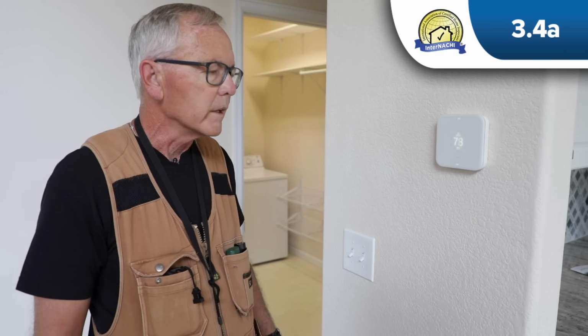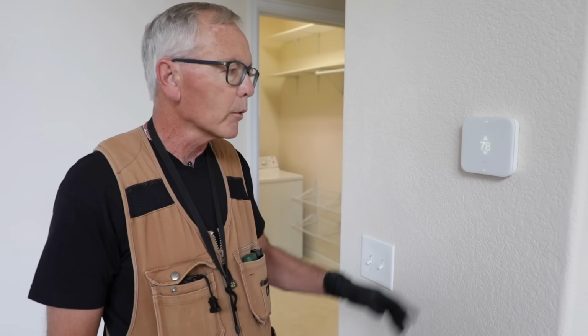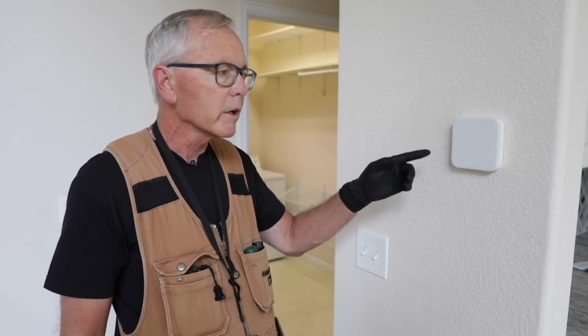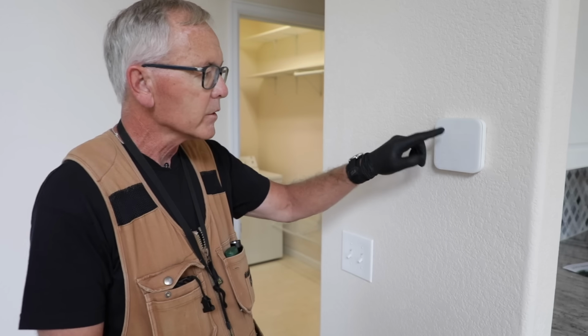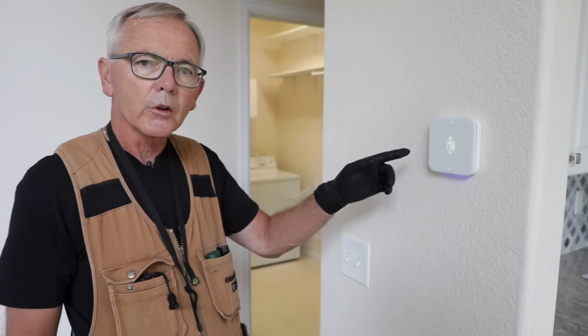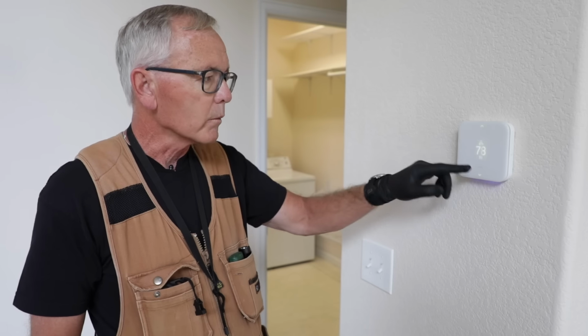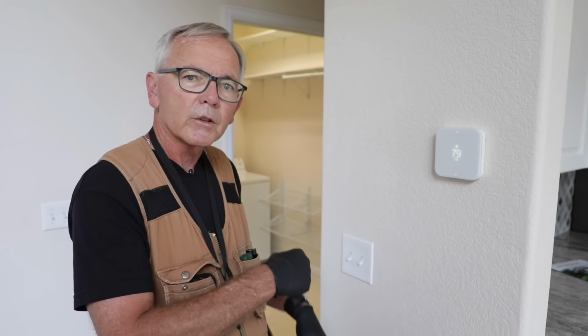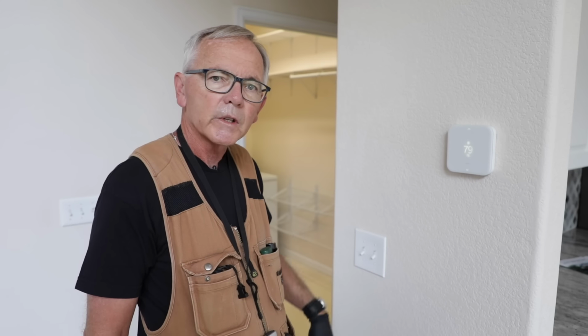This is section 3.4, heating. The inspector shall operate the heating system and describe the heating system using the normal operating controls. The first thing we're going to do is locate the thermostat, and we're here on the first floor. And this is our thermostat. This is a smart thermostat. So we're going to set this up a little bit high so we can go downstairs to the furnace and see if we can get the furnace to engage.